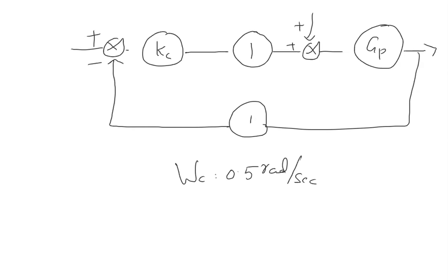Yes, frequency response is always open loop. Then what is Kc? You have to equate the amplitude ratio to 1. Then what is amplitude ratio of open loop?